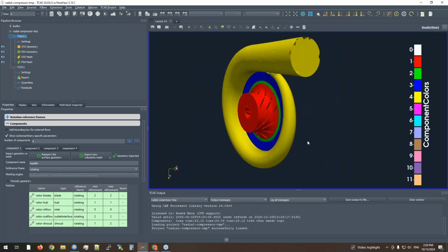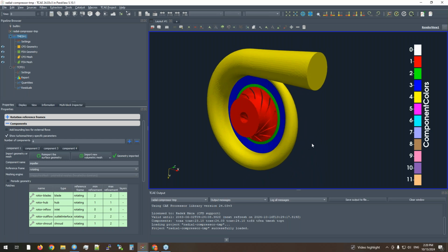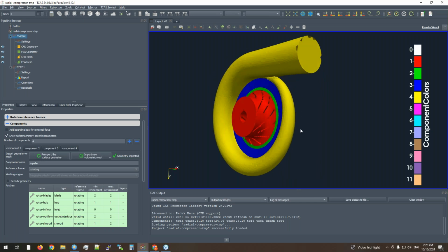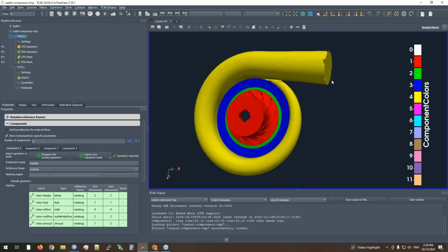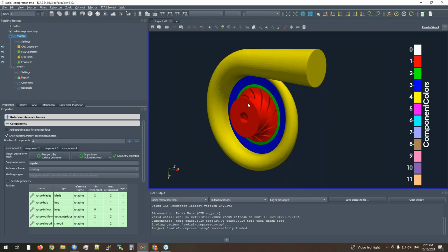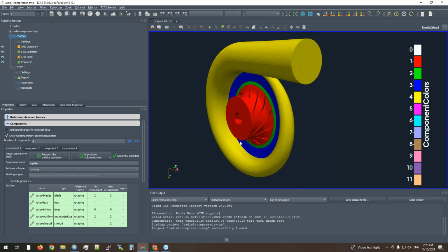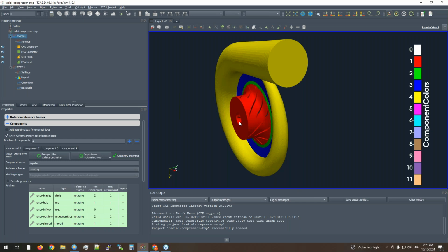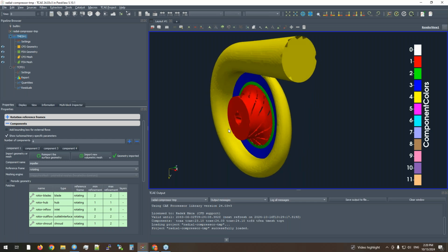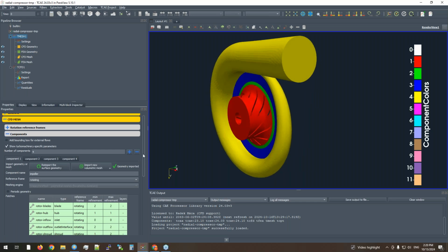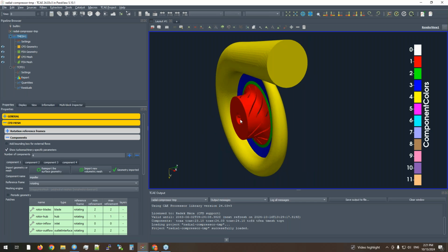And then we have a volute. So for example, for those who are CFD experts, or who work with CFD on a daily basis, it can have a note that the inlet and outlets are too short, because when we set the inlet condition right here, which is typically some total pressure condition or volumetric flow rate condition, which in the easiest way is set as perpendicular shapes.